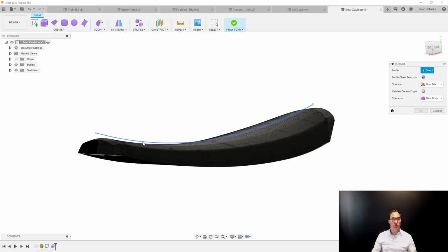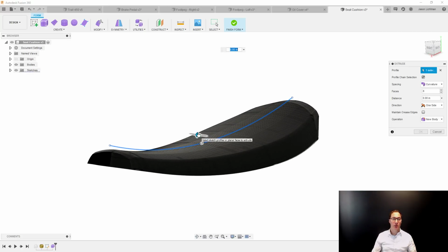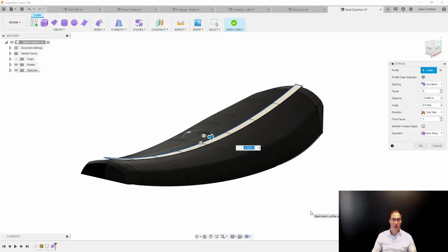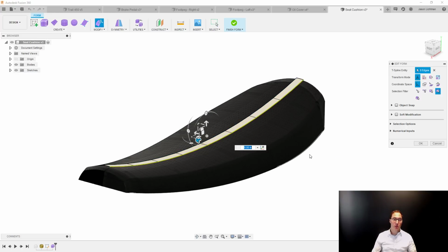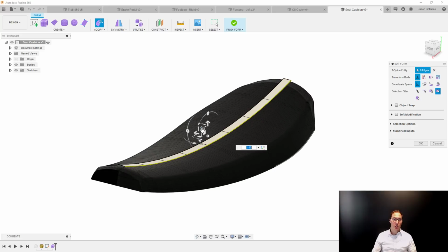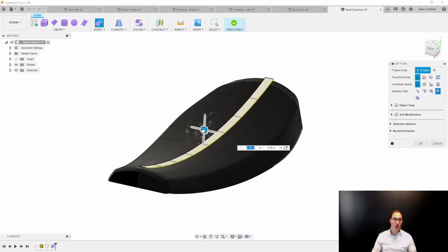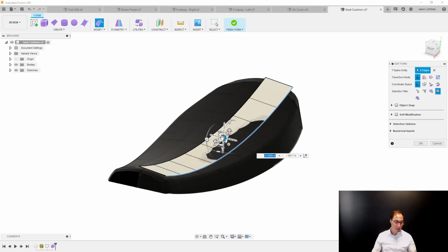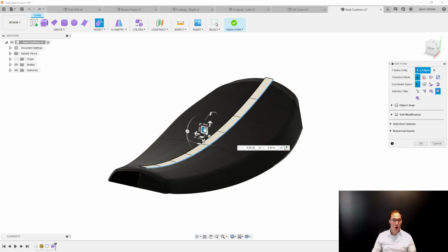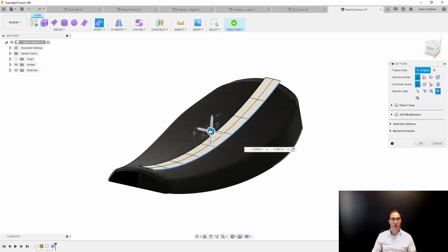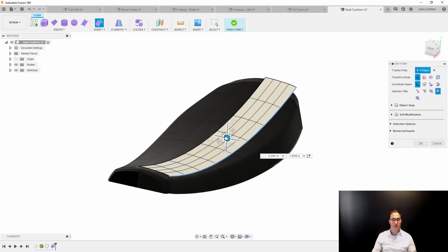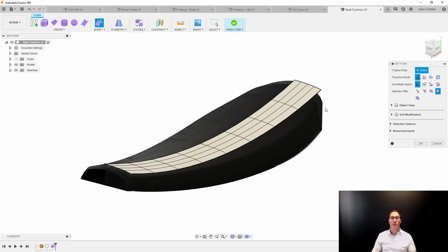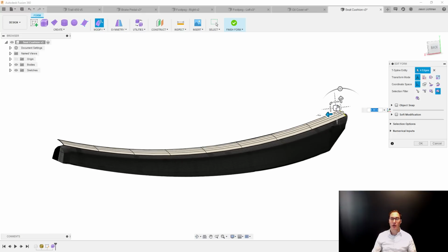We're going to extrude this sketch in this direction just a little bit, and we're going to hit the OK button. I'm going to grab this edge, and we're going to add more geometry. Using my manipulators, I could drag this wherever I want, but I want to create new geometry, so I'm going to hold Alt and then drag this manipulator, and I'm going to start to create new geometry just like this.